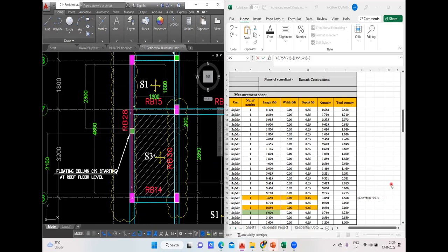Okay. So plus, I open the bracket. I'll directly write the measurement. What was the measurement we got? So this was 1600. I'll write 1.6 into, what is the depth? Depth is 450. And what is the thickness of your slab? 150. So 450 minus 150 is 0.3. That means 300 mm. So 0.3. Getting my point? Plus, again, open the bracket.